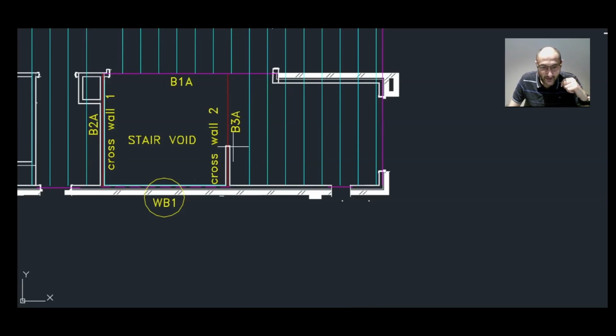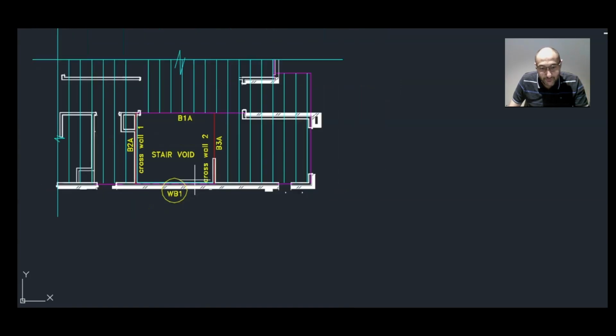And then it will be a good idea to fully brace these cross walls as well to make this bracing element rigid. Now this method is probably a more rigid fixing, which I like, but it's not very practical. Okay, I think extending the beam 900 millimeters or a meter past the void either side and fixing the joist to it is probably a more practical way of doing it.